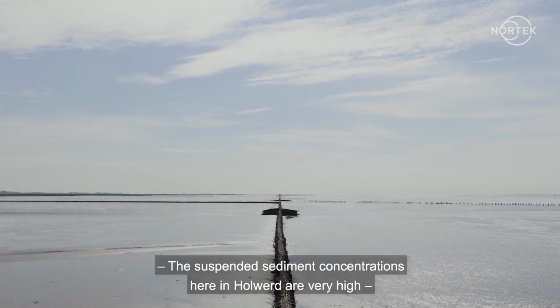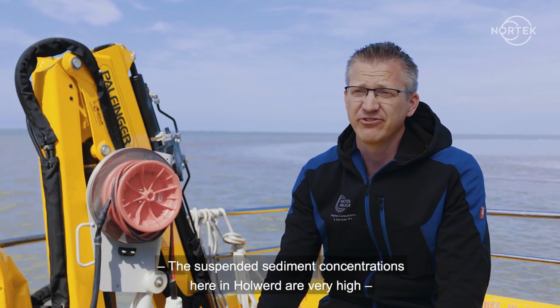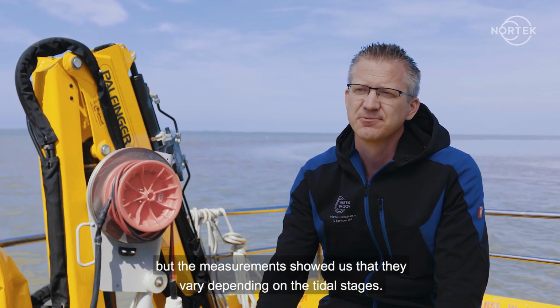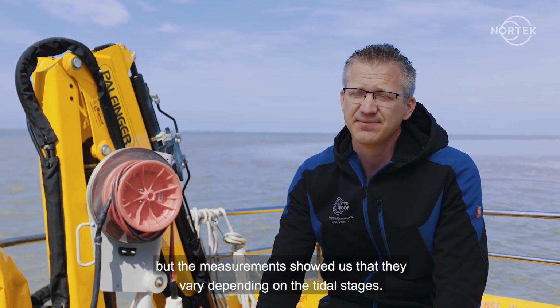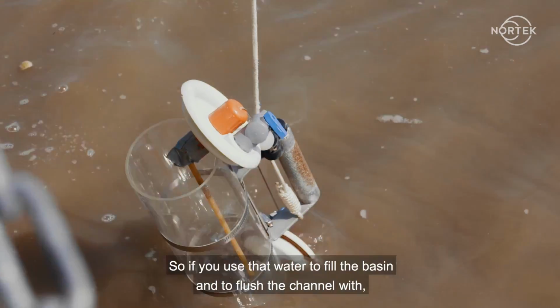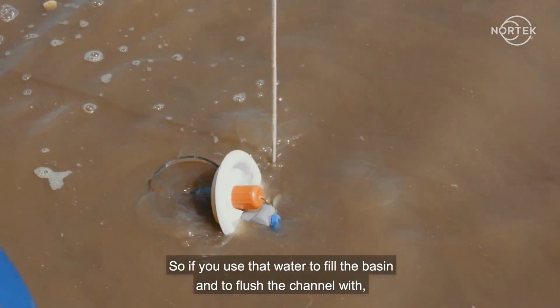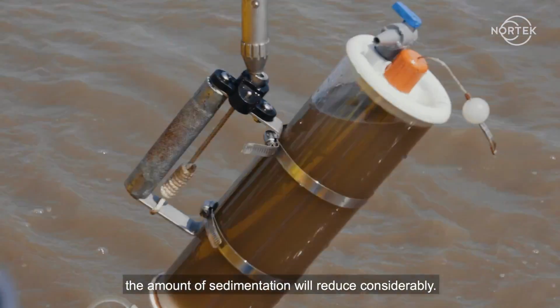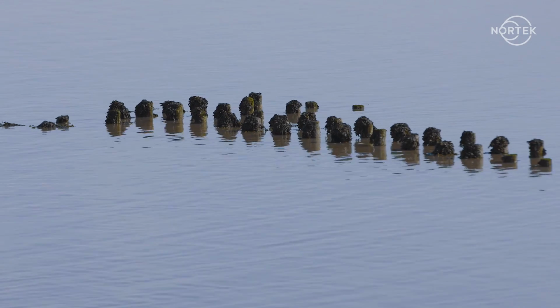So the suspended sediment concentrations here in Holwert are very high. But the measurements showed us that not at all tidal stages the sediment concentrations are that high. Especially during high water, the concentrations are much lower. So if you use this water to fill the basin and to flush the channel with, the amount of sedimentation will reduce considerably.